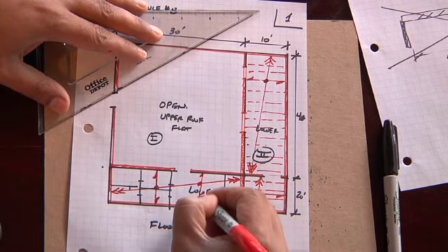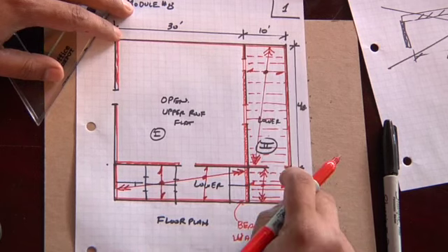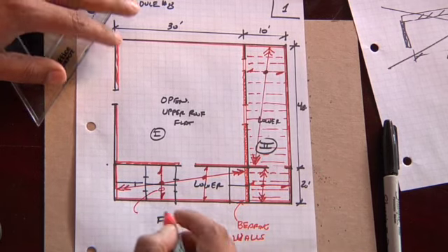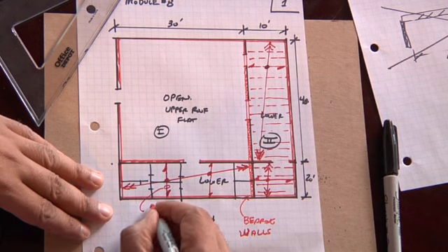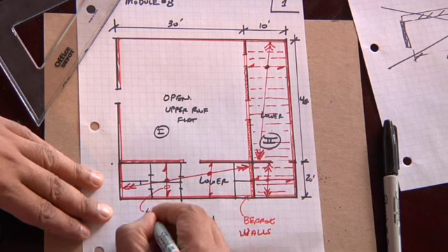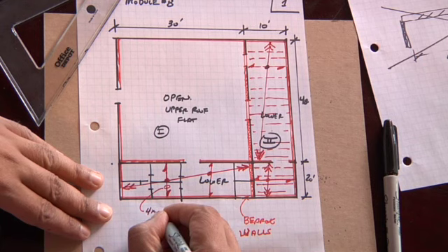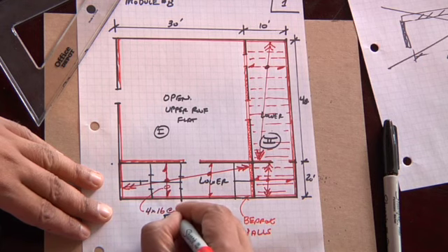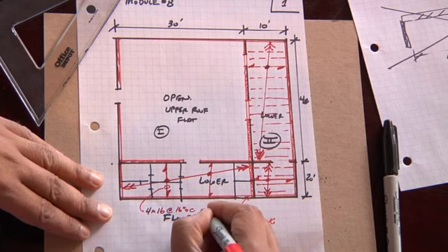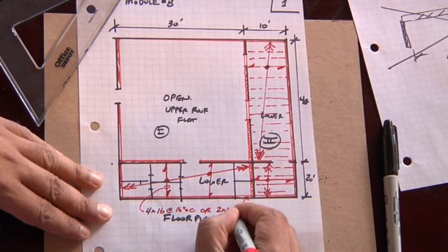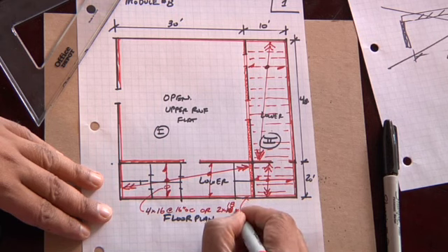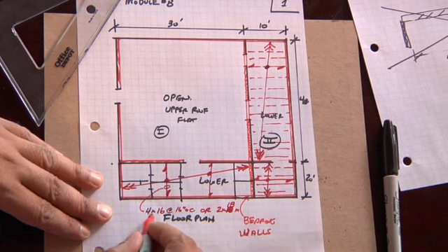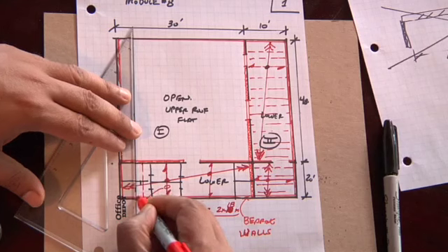That's my joist spacing. And since that's a 20-foot span, I could probably make a reasonable guess. With a 20-foot span, it's going to be a fairly large joist. It might be a 4 by 16 at 16 inches on center, or it could be a 2 by 18, or excuse me, yeah, probably a 2 by 18. That's a little bit large because the depth gets to be a little bit big. Anyway, you don't have to size it. I'm just giving you some approximate numbers. But the exam is going to want you to lay out the actual joists.